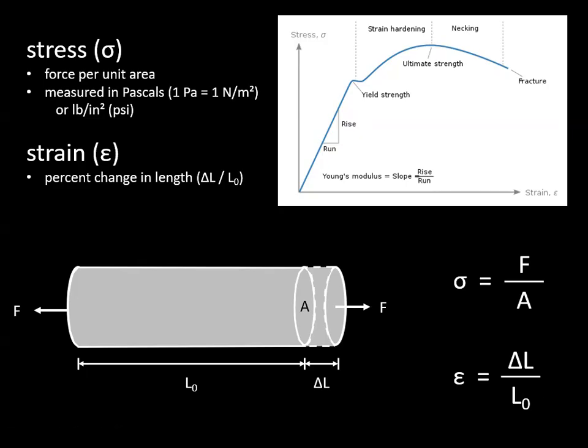What's 2 out of 100? 2%. So strain is a percentage, right? So you guys see percent change in length? Let's see if you really follow what I just said. Get those numbers I just said: strain equals 0.02, right? Do you put a unit after that, like newtons or anything like that? No, it's a unitless number, because it's 2%, 0.02.